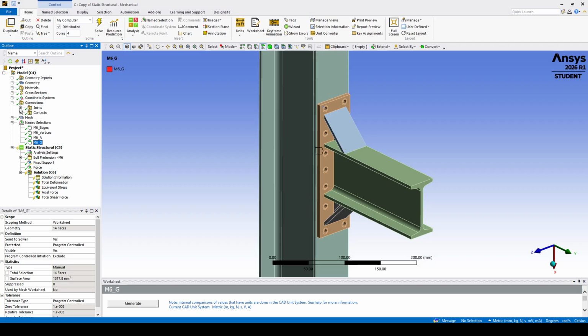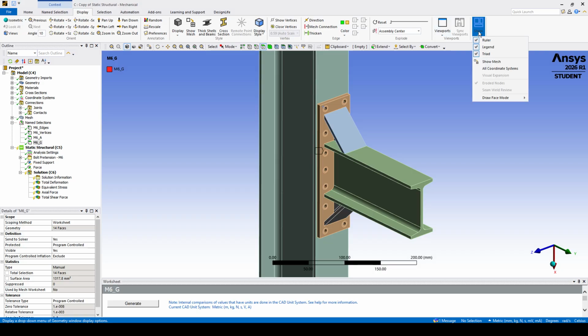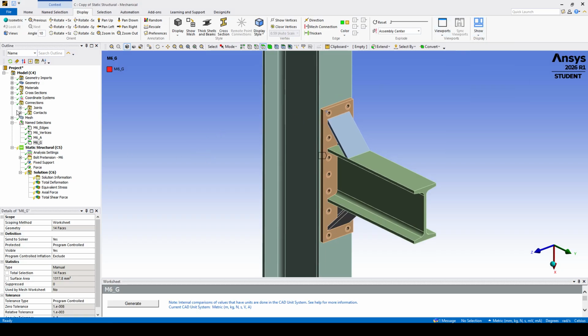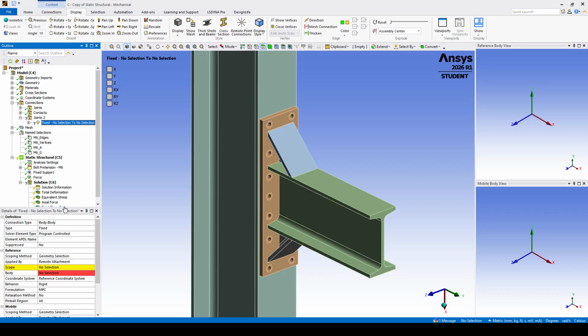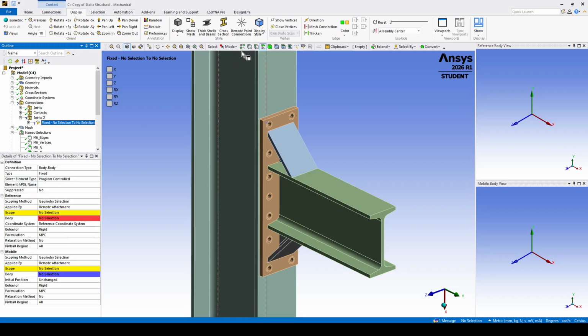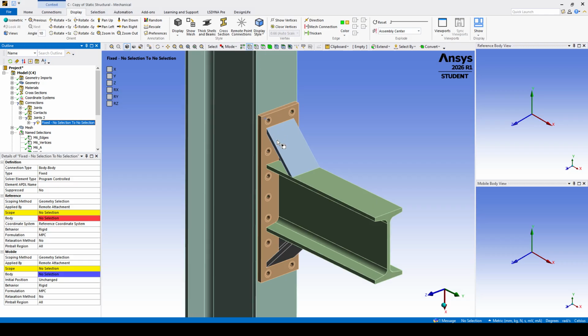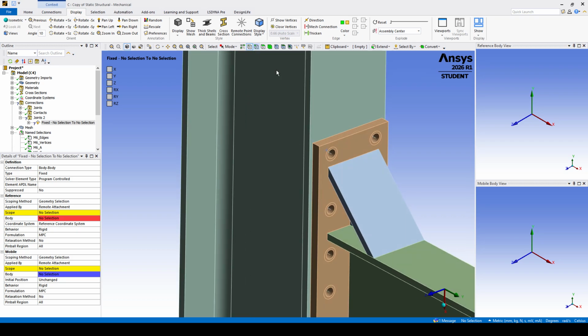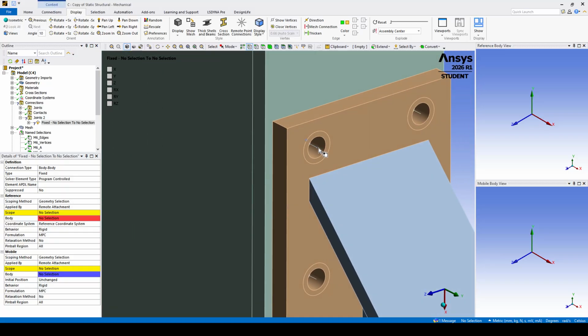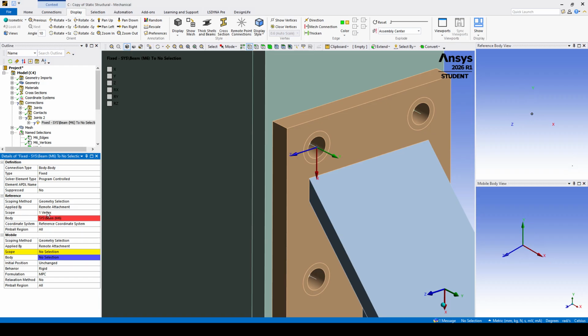Now I'm going to try to create a joint with you together so you can see how to do this. Let's hide the ruler. And for now you go to Connection and Insert, and Joint. All we have to do is go up and choose Vertex, and I have to give it just one example like this. I choose this vertex as a reference, so I click on Reference.